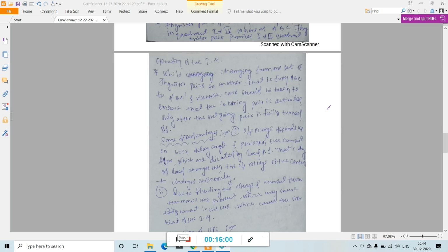In this way motoring and plugging modes appear in the different quadrants, and in these quadrants the speed of the induction motor will be varied. Like in motoring mode, if it rotates in one direction, its speed is at one level and its torque is at one level, then it decreases to zero, and then it increases to the next level of speed or torque in the reverse direction.